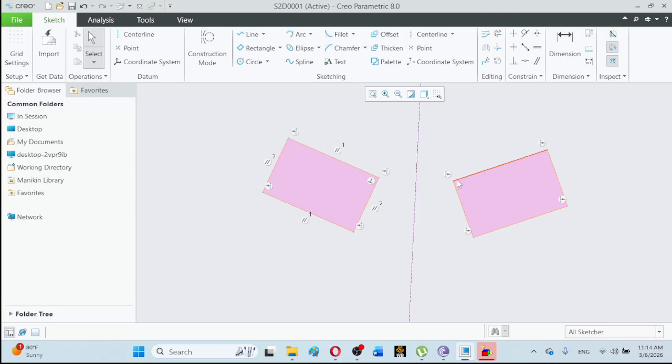So mirror is actually a multiple times application of symmetry. So here if I drag this point, I can observe that it is symmetric about this center line. If I remove this symmetric constraint, these points are randomly controlled. So this point is no longer symmetric or mirrored about this center line.